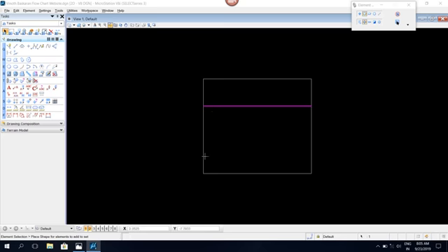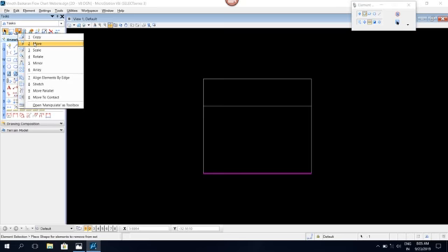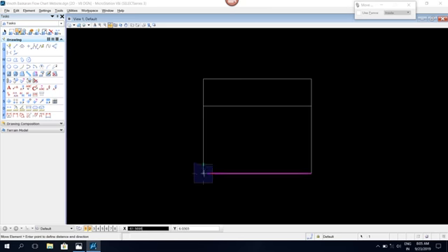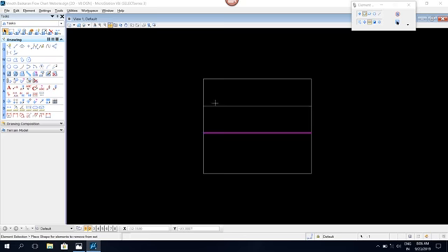Then again we have to create another hidden line, 15 mm offset from the bottom side. For this we have to create another line, the same line here. Again the selection methods; we have to remove other selected objects. Now the line is selected. Then we have to choose the move option. It's in the tasks toolbar, manipulate is the third option, and in this the second is the move option. Again we move 15. It's done. We choose this and do a right click. Now the drawing is completed and we have to deselect all.